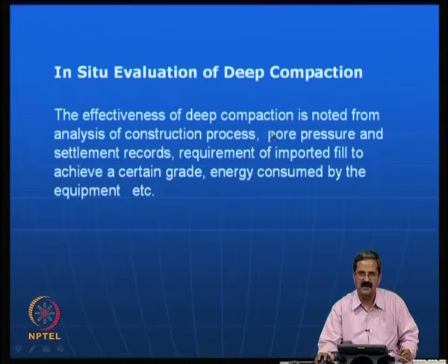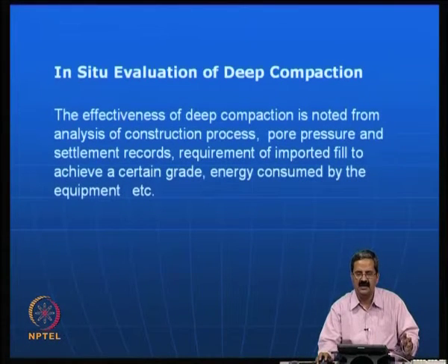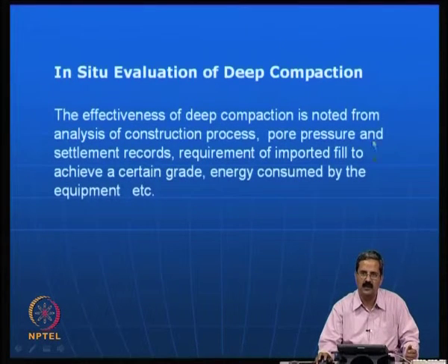The other important thing is pore pressure and settlement records, because pore pressures and settlements are very important. Say for example, you may have initial settlements very high, but the final settlements need to be very, very low, that is subjective. So, you can only get that from settlement records and pore pressure records. As I just mentioned, in the process of dynamic compaction the pore pressure is mobilized because the rate of loading is so high that a lot of pore pressure is generated, and the rate of dissipation of pore pressure tells you what type of soil it is.